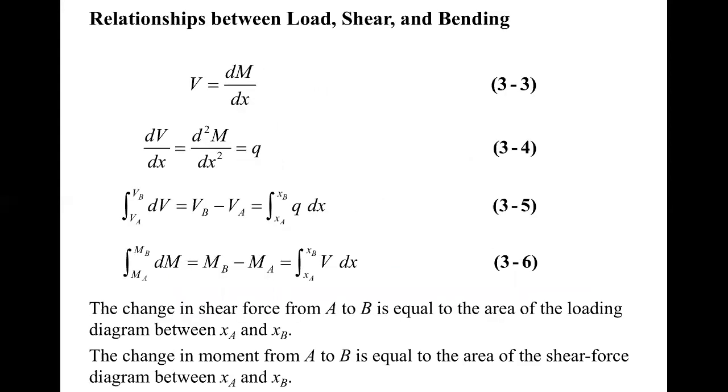For distributed loads, because Q is a function of X, basically we can have those equations. Those equations sound familiar. Let's look at the transverse shear. V equals dM over dx. If you have the bending moment, you take the derivative of bending moment with respect to x, and you'll get a shear.